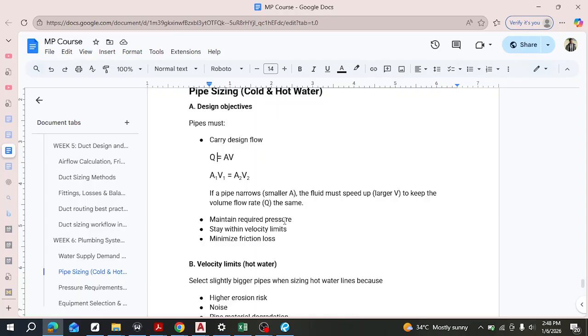Okay, pressure does not really drop over a distance. There are different forms of pressure. There's static pressure, there's dynamic pressure. So it doesn't really drop. Let me just talk about static pressure because I've mentioned it. Static pressure is the pressure at a particular point in a pipe. And the higher the velocity of the flow in that pipe, the lower the static pressure, and the lower the velocity, the higher the static pressure. So understanding the pressure-velocity relationship helps you to design better.